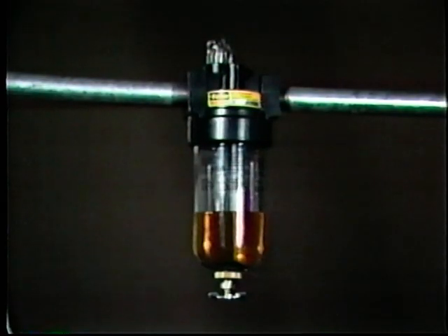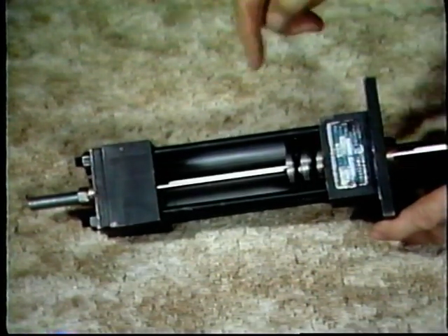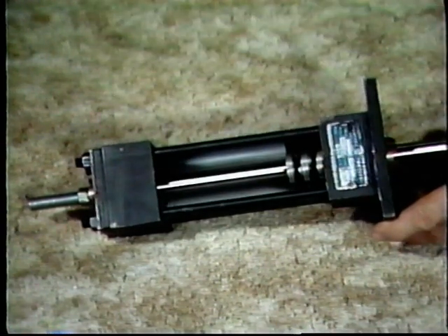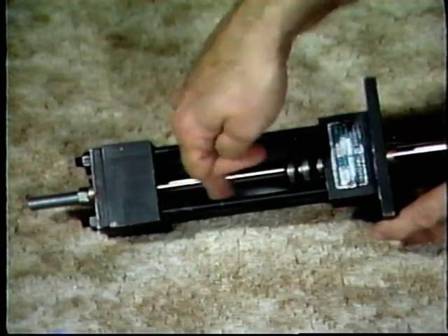The device you see here helps to ensure trouble-free operation of pneumatic system components. It's an airline lubricator. Except in those systems designed for oil-free air, pneumatic components like cylinders, motors, and air tools must be lubricated if they are to work properly. So the lubricator actually puts oil into the air that feeds them. And when the air reaches the equipment, it spreads a lubricating film over all exposed surfaces, like cylinder walls and seals.